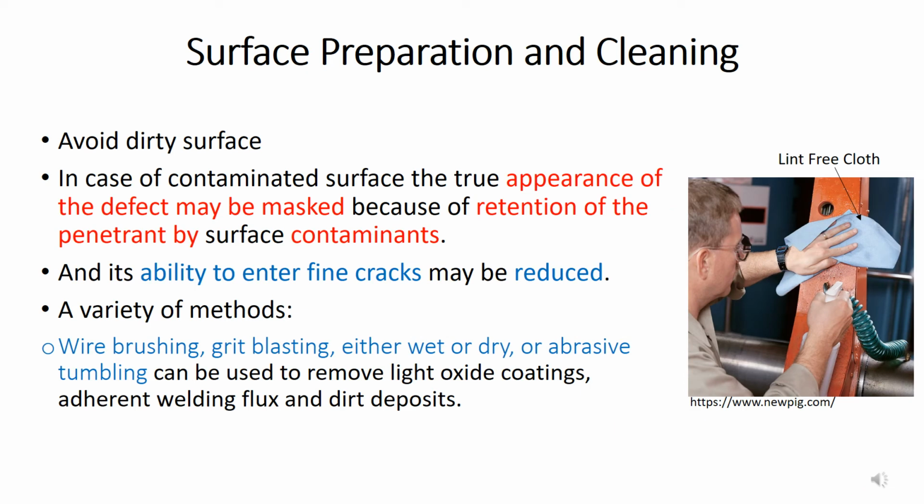The first process, which is surface cleaning, is a very crucial and important step. We should avoid a dirty surface, because if the surface is dirty and has contaminants, then the penetrant will be retained by the contaminants, meaning it will be stopped by the contaminants, and the penetrant will not be able to seep inside the cracks.